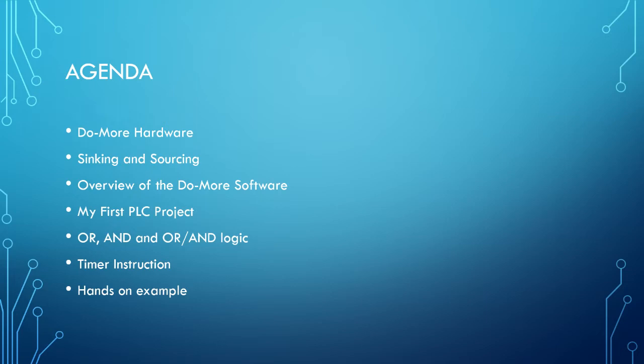And next class, we'll be testing our PLC project and simulating. It's very important to learn how to do the simulation, use the Do More simulator in order to understand how to use it, especially because you'll be simulating a lot before taking it out to the PLC. It's rarely that you don't simulate in an environment where it's not dangerous. You want to make sure that the project actually works before you take it out there.